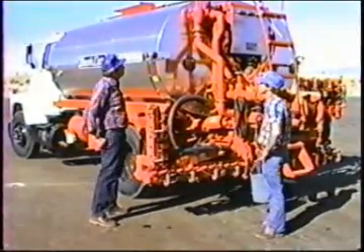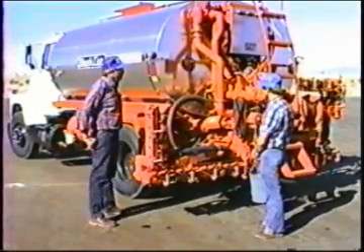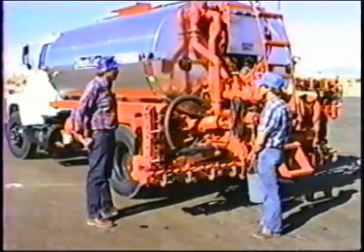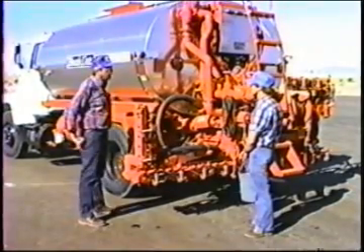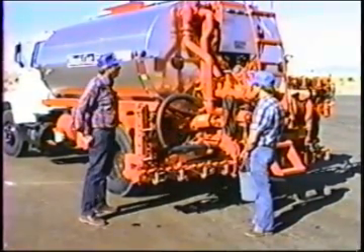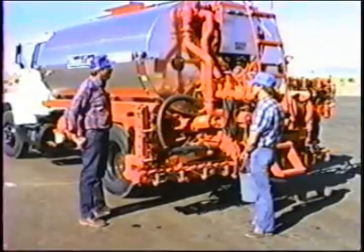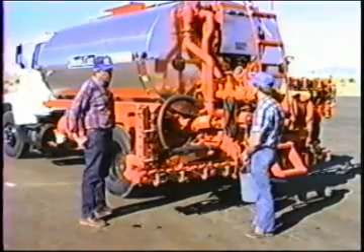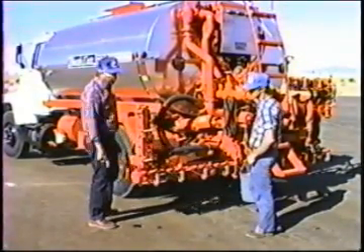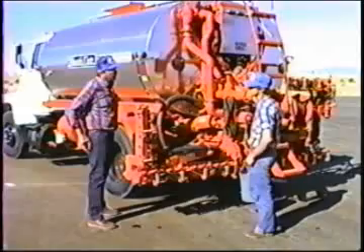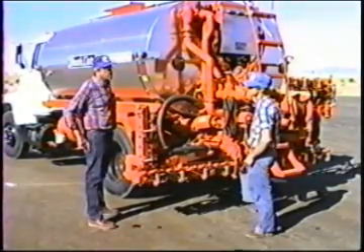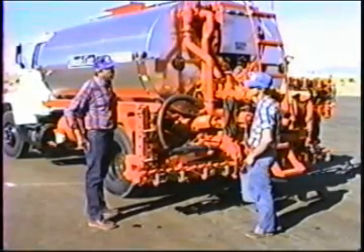Bill, now we're going to talk about spread rate. There's two purposes for all this high-powered machinery. First purpose is to put the asphalt down in the right place. The second purpose is to put it down at the right rate. Again, we're going to talk about gallons per square yard. That's the common nomenclature for what we put down with an asphalt distributor. And that is, if we have 3 feet square on the ground, 36 inches by 36 inches, that's a square yard, we're going to evenly distribute a part of a gallon over that.